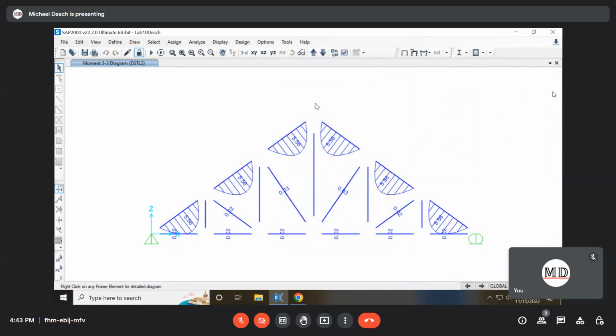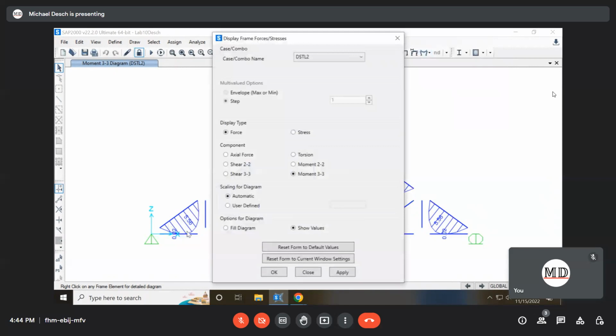Right, yeah, I selected all of them. I set the output station to 9 on all of them. If you look at shear, it'll be the same diagram shape. It's just going to have more of these lines in the middle because it's evaluating at more output stations there.